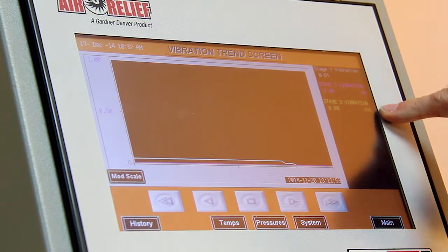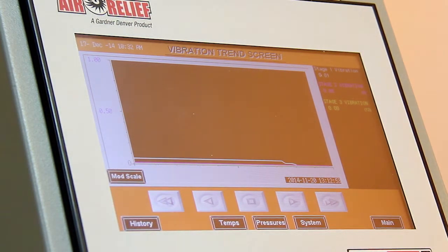And in this situation, we would bring in stage 3 analog vibration on input number 12. Now, analog inputs, I should say, are labeled 0 through, for example, 25 or 23, I'm sorry. So your analog inputs start on a 0 basis, and then they're numbered up from that point.